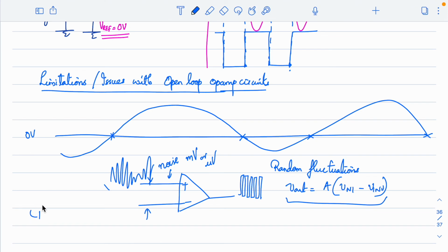So the remedy here is to establish positive feedback in the circuit, right? Why do we say that positive feedback is required? Because we want to make a decision, and the decision is the logic levels, or in this case, switching between plus and minus Vsat. The positive feedback mechanism can give the same, but at the same time it should eliminate the issue we discussed now, right?